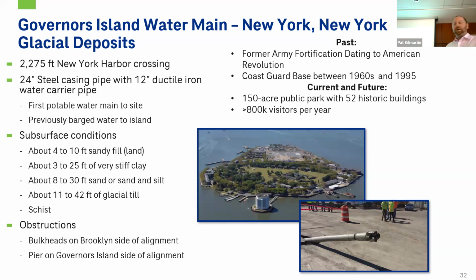But they're going to need a mud pit in order to construct this. And so especially for this drill being 2,200 feet, it's going to be at least a 5x5 area that they take out of the slab. This was kind of a dock pavement area, so it wasn't a major concern. But ultimately, at a minimum, even for your smaller drills, you're going to need a pit of at least a bucket or two width of an excavator and probably 4 or 5 feet long to contain that mud, or else the mud will just spread over the entire area. So no matter what, you need to have somewhat of a pit at that location.